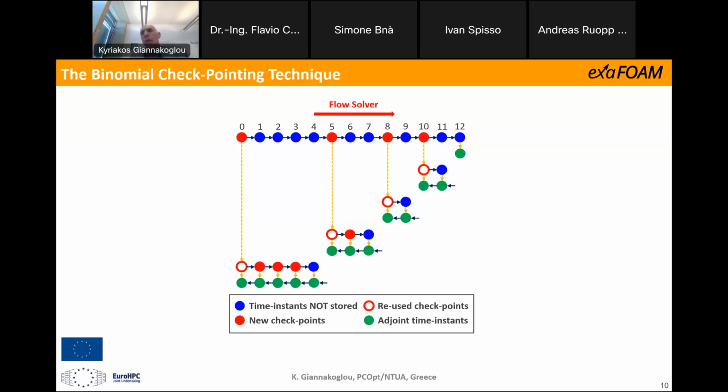To retrieve flow fields at time instants other than checkpoints, what you have to do is to use the flow solver to integrate again the flow equations forward in time, starting from the last checkpoint. It is for sure that already used checkpoints should be relocated into the time span.